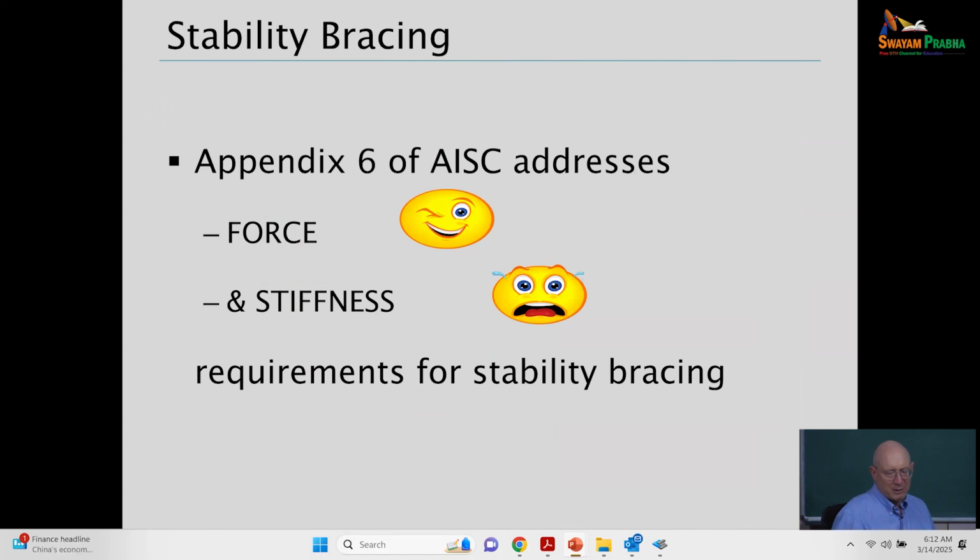All right, so traditionally, engineers would often handle column bracing simply by a rule of thumb, such as, oh, I need to design my members that are supporting the column out of plane for, say, 2% of the load in the column. We're going to find that the rules in Appendix 6 actually are relaxed relative to that. The force or strength requirement tends to be smaller than that.